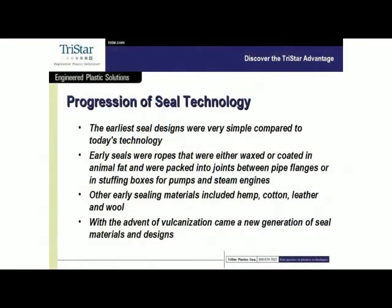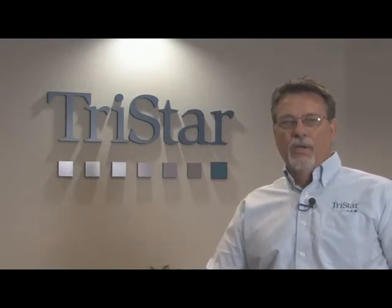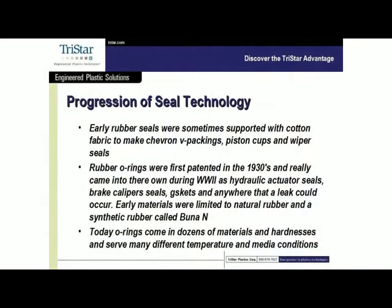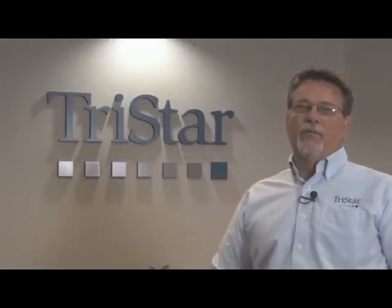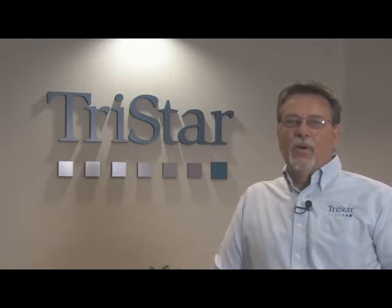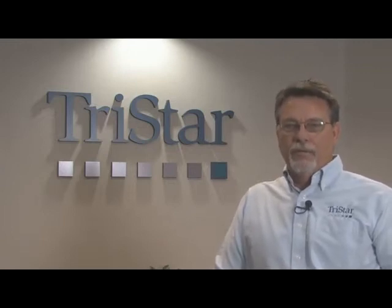With the advent of vulcanization came a whole new family of products. Rubber seals came along, both for gaskets and eventually, in the early 30s, we saw the advent of rubber O-rings. Early on, the rubber seals were sometimes reinforced with cloth or cotton just to give them a little bit of reinforcement. And some of those early designs were chevron packings. Even today, many pump packings are still chevron packings made out of rubber and cotton cloth. So even to this day, with technology being what it is, there are some things that still work best, even though they're the simplest design.